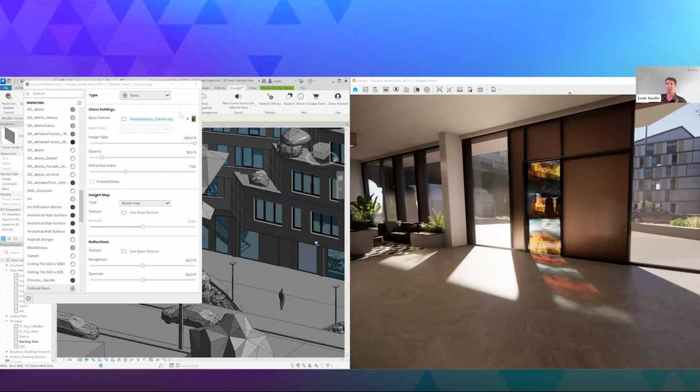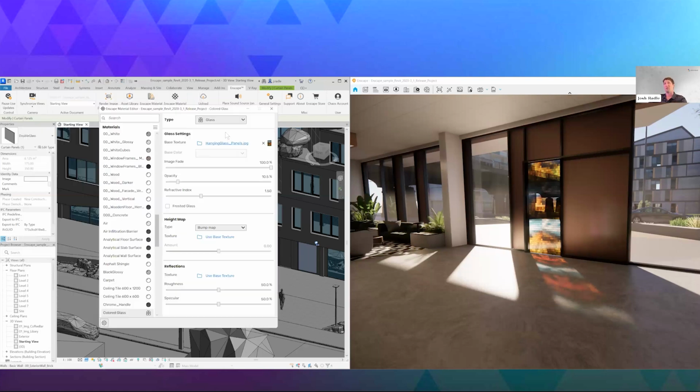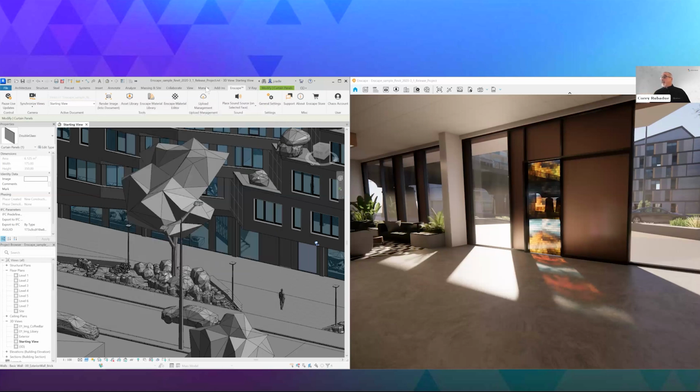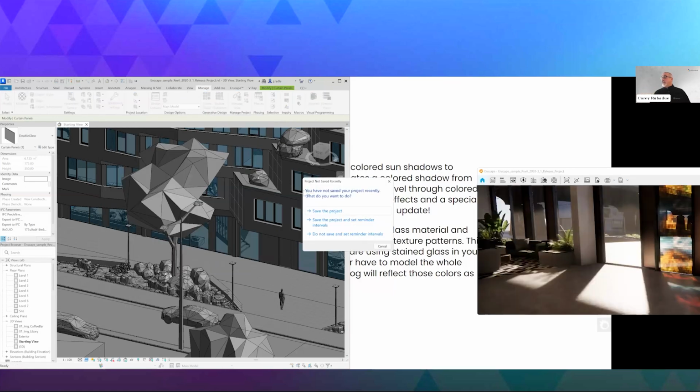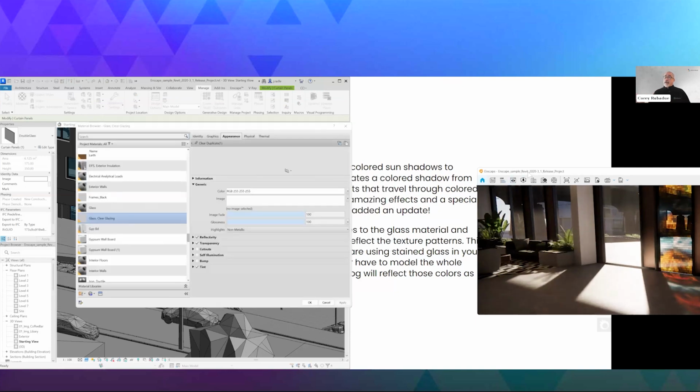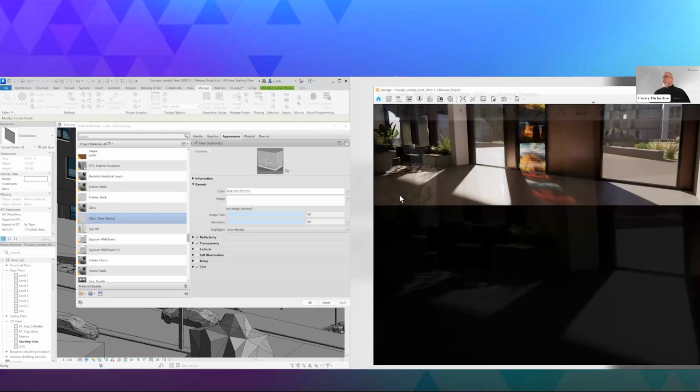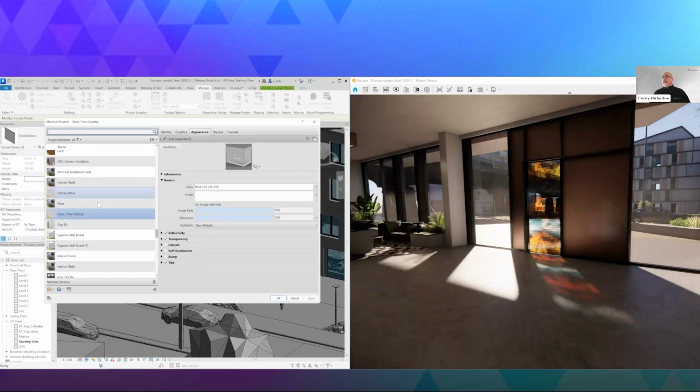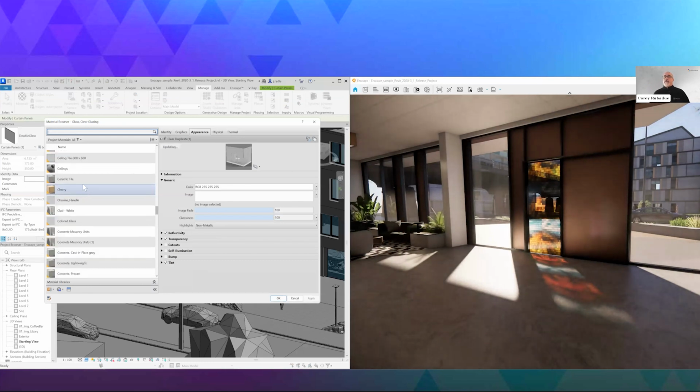And one thing for those that might not know, anything you're changing inside of this Enscape material editor will push back inside of Revit, or whatever host design application you're using. So in this case, Revit. This material is going to show up inside your Revit model now. So that's bi-directional, right? Yep. If you're making design decisions and applying them to your Enscape scene, it gets back into your Revit model material there, and people can see it directly in the project.